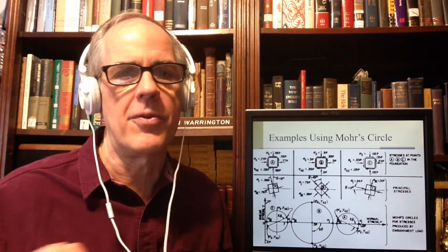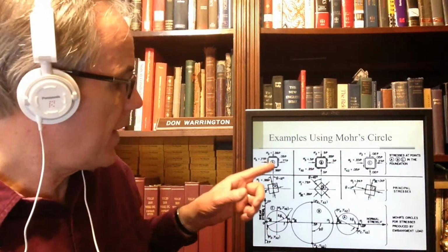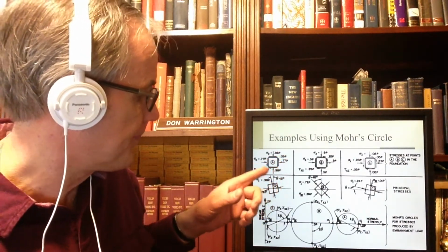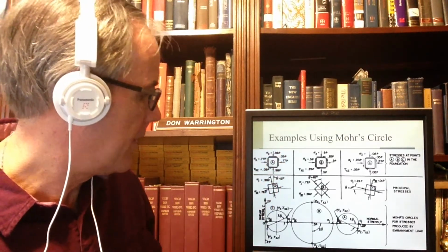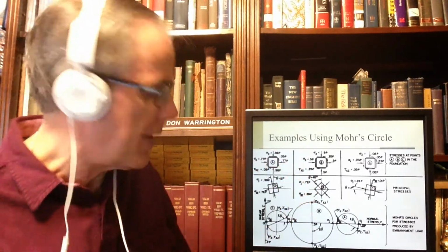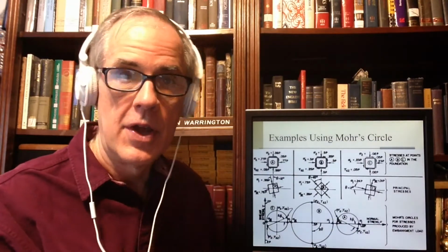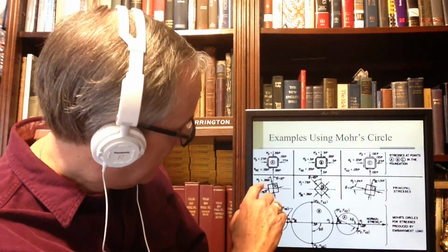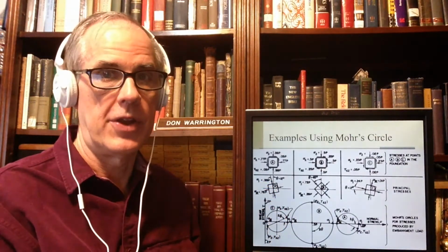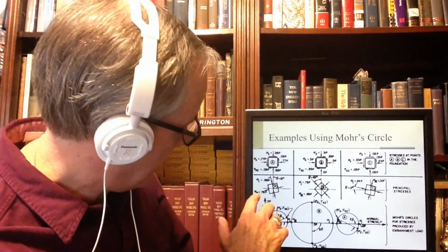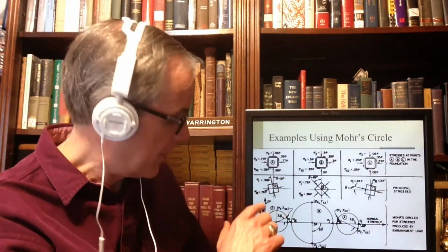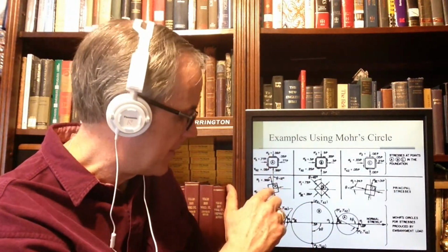We're going to quantify that when we get to lateral earth pressures. And then we have these small shear stresses, 0.6p and whatnot. That's a nice stress state. If I were to rotate that 12 degrees this way, what I will end up with is the principal axes, which means that the sigma 1 is 0.99p. It's almost a uniform surcharge state. And the sigma 3, they use, this came from NAVFAC DM7, they use Roman numerals for whatever reason, is 0.76. Not much different, but some.